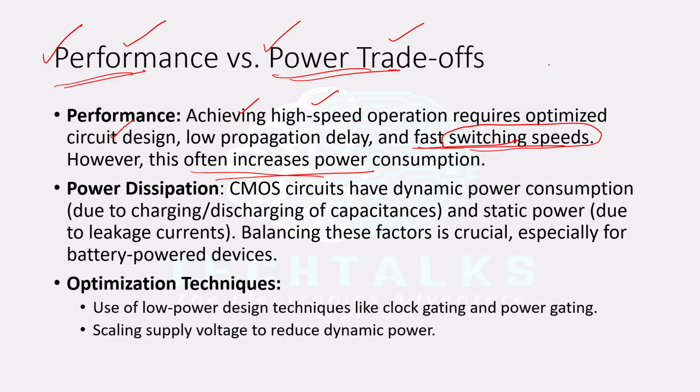we'll be adding so many MOSFETs in parallel, which in turn will lead to a larger power consumption. As MOSFETs are added in parallel, any MOSFET you can remember as a simple resistor when it is on, let us say RD.